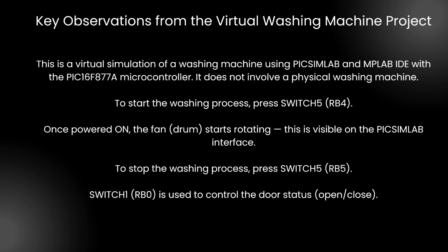The key observations. The project is fully simulated in the virtual environment using PICSIMLAB and MPLAB IDE. No physical washing machine hardware is required. The switch 5 we are using starts the washing machine process, initiating fan rotation visible in the simulation, and switch 5 also stops the washing machine process, and switch 1 simulates the door sensor, preventing operation when the door is open. And real-time system feedback is displayed on the LCD display.